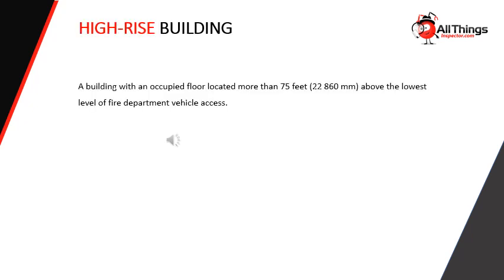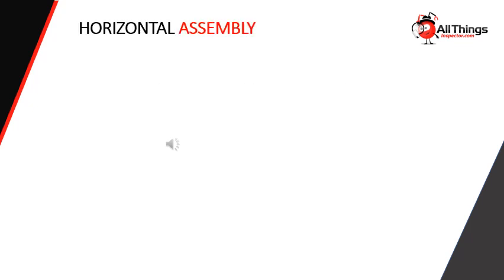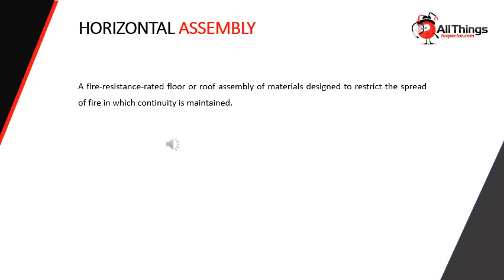High-rise building. A building with an occupied floor located more than 75 feet, 22,860 millimeters above the lowest level of fire department vehicle access. Horizontal assembly. A fire resistance rated floor or roof assembly of materials designed to restrict the spread of fire in which continuity is maintained.